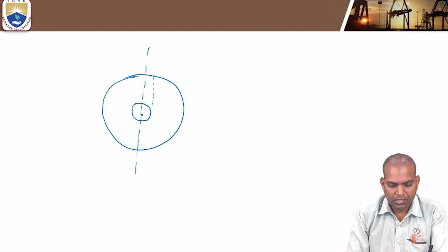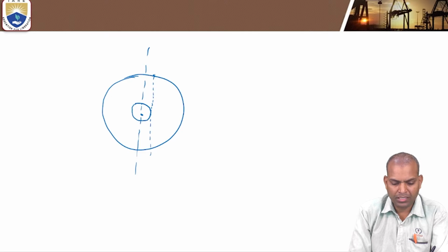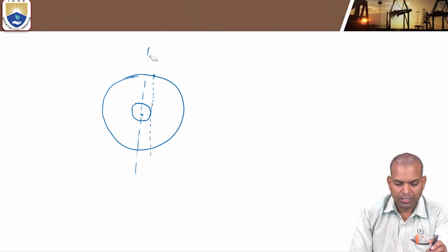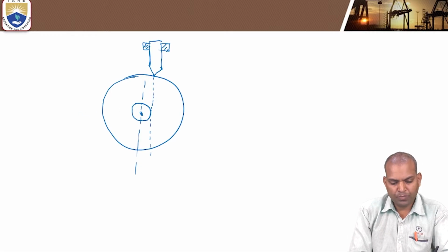Now, touching the tangential surface of the offset circle and intersecting the base circle at the top, at the circumference, this is the point where the roller is in contact. So join this base circle center to the tracing point.